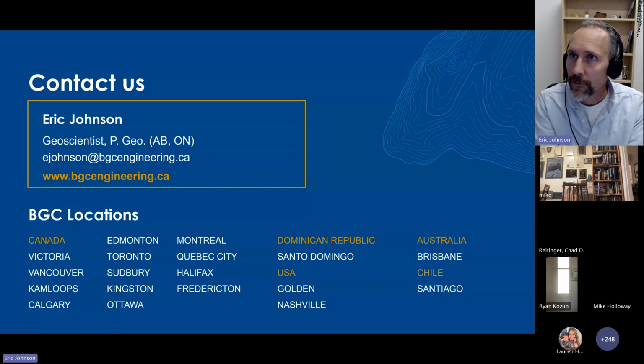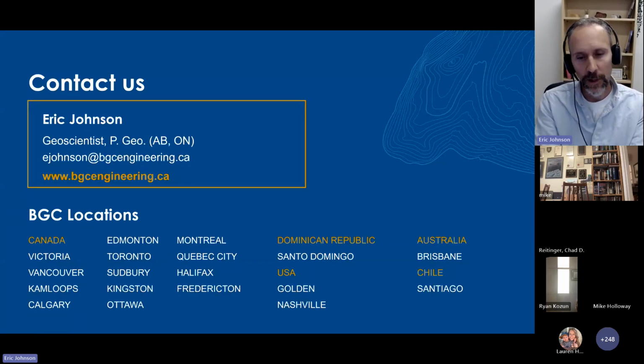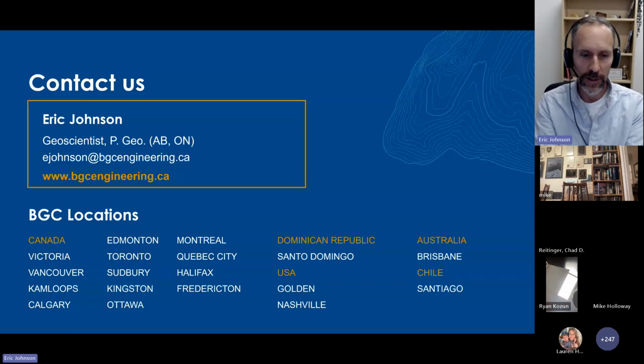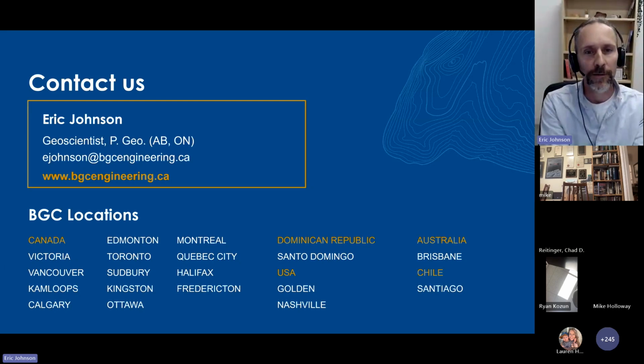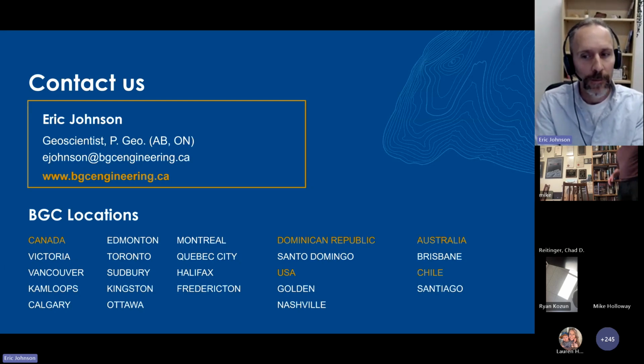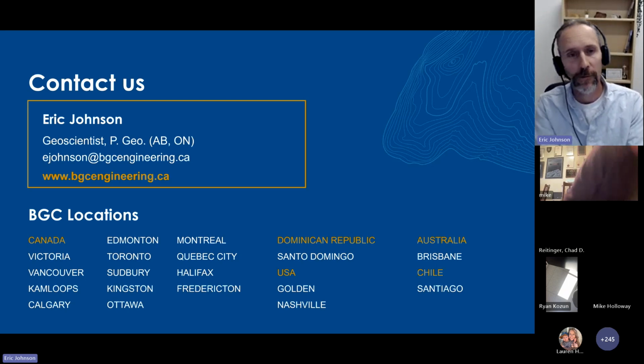We didn't take that information into account. I didn't have that available at the time, but what's really nice about this Python approach is that it's site specific. So any additional information that we do get like that can easily be added. The next thing I really wanted to add, if I can get my hands on the saturated versus unsaturated information, is to have that same plot colored just like it was, but with different symbols for the saturated and unsaturated values. You'd expect to see lower resistivity values for saturation. So anytime there's any information like that, we're happy to include it.